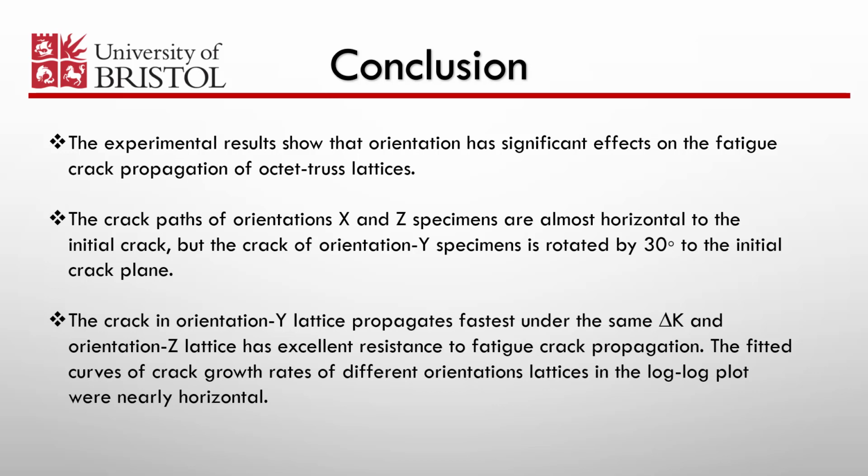The crack in orientation Y lattice propagates fastest under the same delta K, and orientation Z lattice has excellent resistance to fatigue crack propagation. The fitted curves of crack growth rates of different orientation lattices in the log-log plot were nearly horizontal.